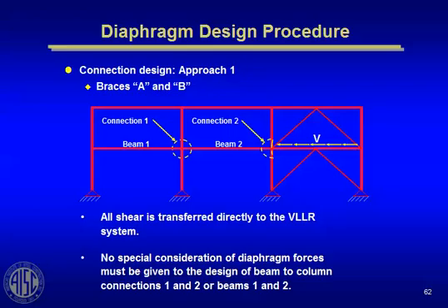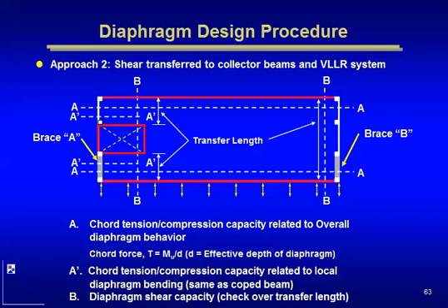However, when you get into high seismic zones, when the big buildings that are big masses and you can get some really heavy seismic shears generated, you may not be able to resist all the shear within the width of the lateral load resisting system by itself, and instead we have to rely on additional width, these collector beams, to help carry or collect some of that shear.